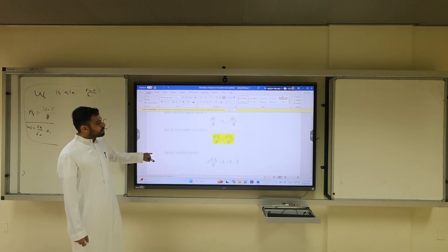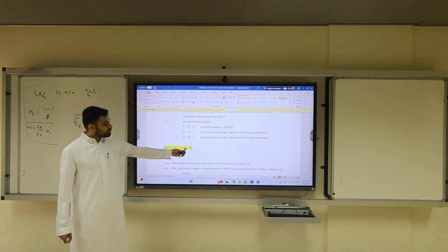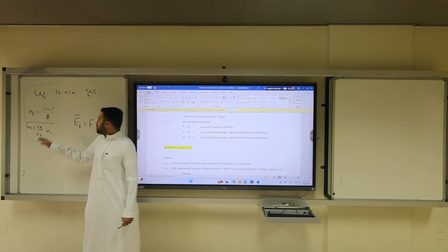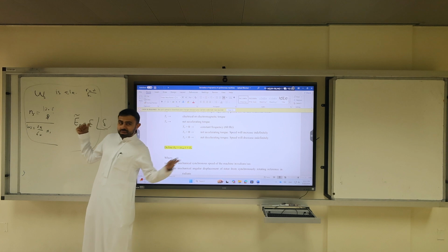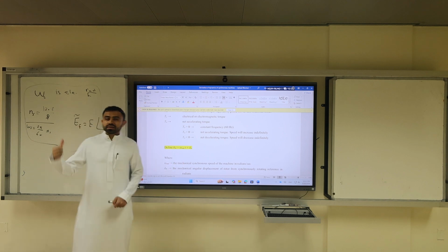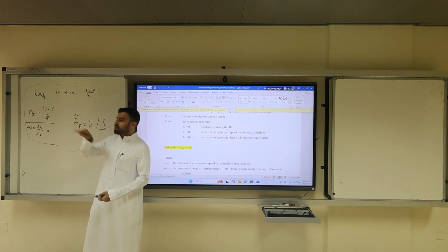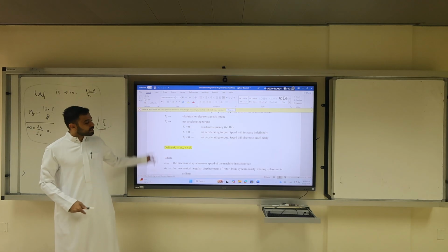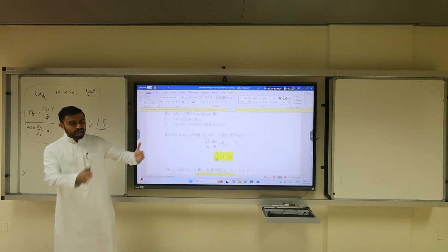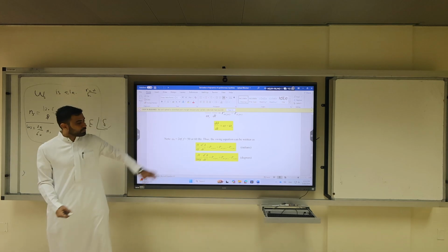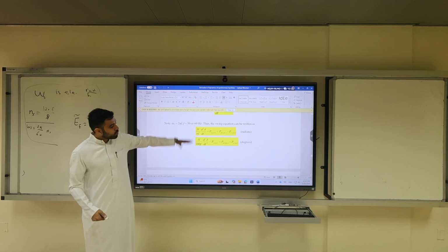It's the one here, theta_m equals... this is delta sub m. M means mechanical. What's the difference between delta_m and delta? One is mechanical, one is electrical. The electrical one you calculated by measuring the voltage, E_f. You measure V_t, you measure I_a, you know E_f from the electric circuit. So in the swing equation now, we have transferred every mechanical thing from mechanical engineering to everything electrical.